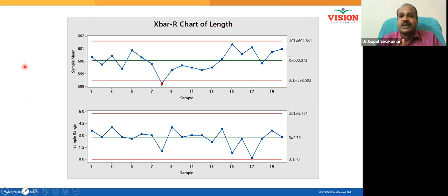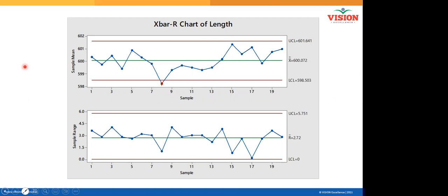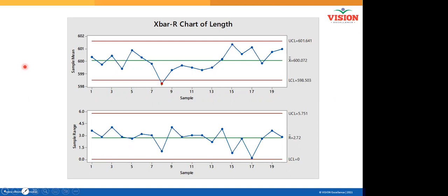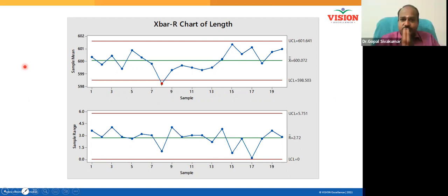See, the R chart is a sample collected over a shorter time. Do you understand? If you are not consistent over a shorter time, will you be consistent over a longer time? No. So, first of all, achieve the short-term consistency. Shift-wise consistency you should achieve. One sample per shift is good enough, which means I have standardized the process. I take one sample in one shift. I am very sure the next 8 hours the same thing will continue. You understand? Only when the shift is changing, operators are changing, there is a chance for variation.